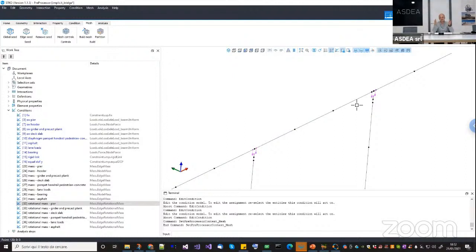you can obtain the exact solution for a force beam element with just one element for each member. But this is not true, for example, when you want to do eigenvalue analysis, because you cannot obtain the exact eigenvalues with just one element. Or for example, when I'm using the co-rotational transformation, if you discretize your model, large displacement and rotation will be captured better.